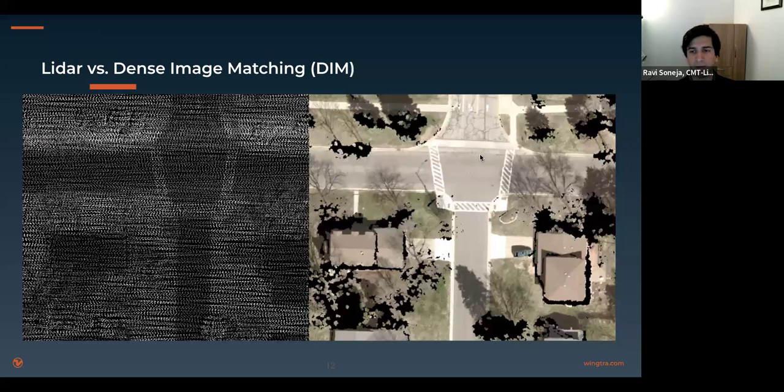We were doing LiDAR and imagery. These flights run pretty fast, we found. I'm actually surprised at how much ground we can cover in a single flight. And not to go on a tangent here, but we just did our first live project in North Raleigh, and it was an 80-acre site. By the time we accounted for flying out and covering all the control points, we're at 240 acres, and that was done in 20 minutes, and I think we still had 10 minutes worth of time that we could have kept flying. So from the processing standpoint, Justin, I'll let you take that.